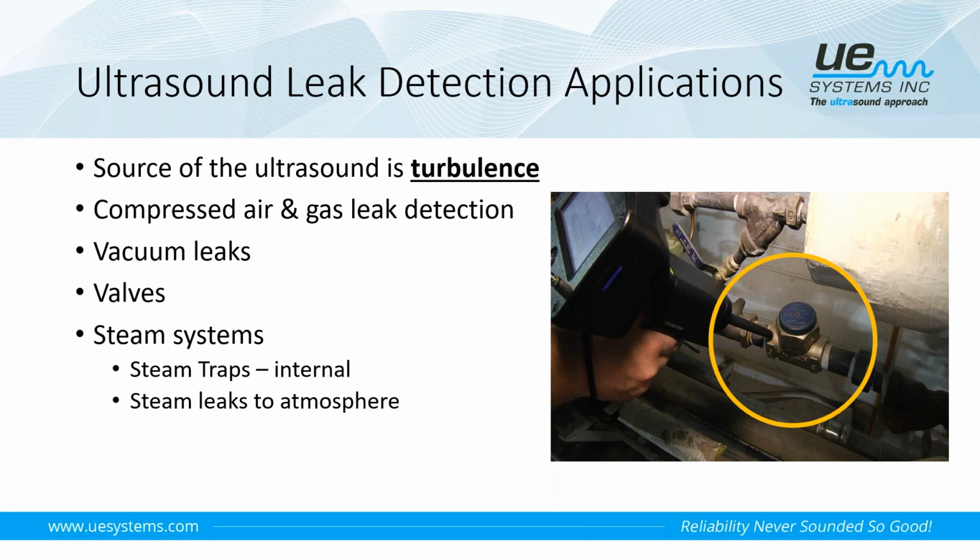Now, valves, that's also going to be a contact application, where we can check valve leakage, very similar to the way that we inspect steam traps. We'll be able to determine if that valve is in the open position, if the valve is closed, or if that valve is leaking by. And again, that's going to be physical contact with different points along that valve, two on our inlet side of the valve and then two on the outlet side of the valve.